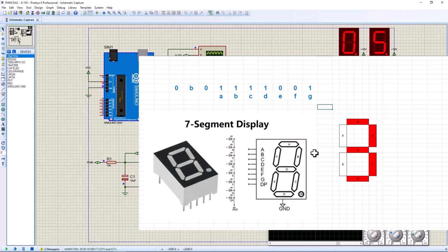And this is where the shift register comes into play, right? With the shift register, you can just use 3 IOs and connect it to the display, and it will cleverly drive your 7-segment display. So now let's see how a shift register can be used to light up the 7-segment in a way that gets the digit that you want.